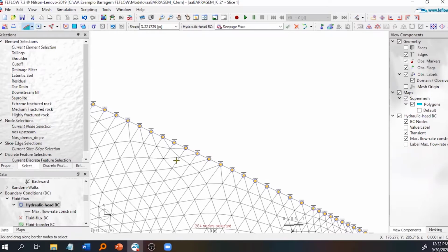Not in FEFLOW. In FEFLOW, it pumps until the water level inside the well goes to a minimum. Then it stops pumping and allows the head to be calculated. You constrain by a maximum. Let's say you also have a system that turns on the pump if it goes higher than a certain level, you put also a maximum constraint of heads, and then you have a more realistic function.